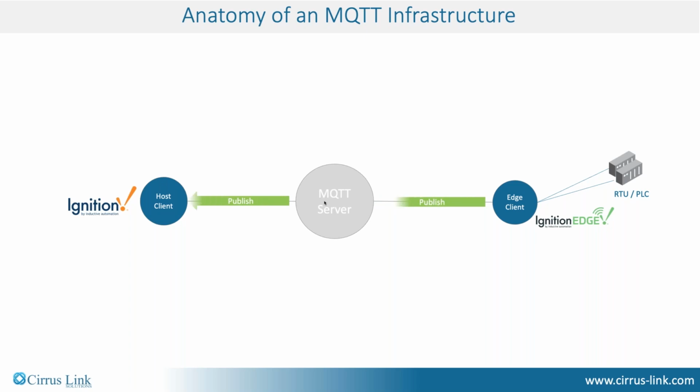So one of the huge advantages of MQTT is that we've shown over the last 20 years that if we replace a poll response system with an MQTT infrastructure for the same tags at the same update rate, we get an 80 to 95% bandwidth reduction. Now, in 1999, when Andy and I did this, that meant an 80 to 95% reduction in their communications costs. But in 2020, I think that means that is 80 to 90% more stranded information that we can bring in over the same bandwidth.